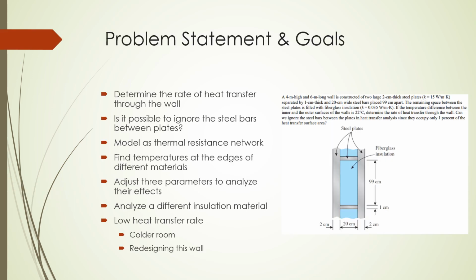First, we're going to dive into the problem statement and a couple goals we have. So, the problem statement is a 4-meter high, 6-meter long wall constructed of two large 2 centimeter thick steel plates, separated by 1 centimeter thick, 20 centimeter wide steel bars, placed 99 centimeters apart, and that remaining gap between the steel plates is filled with fiberglass insulation.